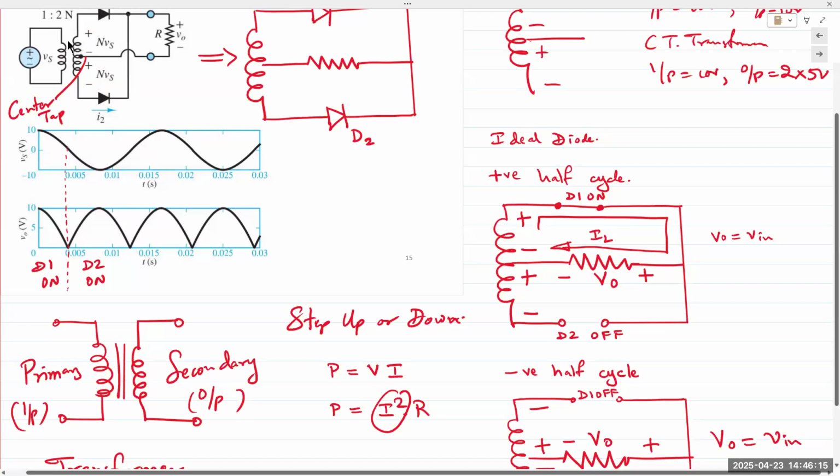The question being asked is what happens if both D1 and D2, or just D2, were flipped. If just D2 was flipped, I believe you answered it yourself: in the negative half cycle, we would obtain a negative output. That would be very interesting actually. The positive half cycle would have positive voltage, the negative half cycle would have negative voltage. So if you had two LEDs connected, they would alternate, flipping. But yes, that's the answer.